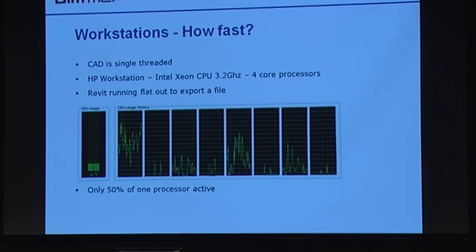So you need the fastest workstation you can get, but because they hit a clock ceiling about 8 years ago, workstations these days are only really improving in speed because of the graphics card, which affects it a little bit, and the operating system going out to 64-bit, which allows you to use the memory and get some sort of improvements out of them. But a workstation today for CAD and a workstation 5 years ago with the same operating system will probably give you very similar performance.